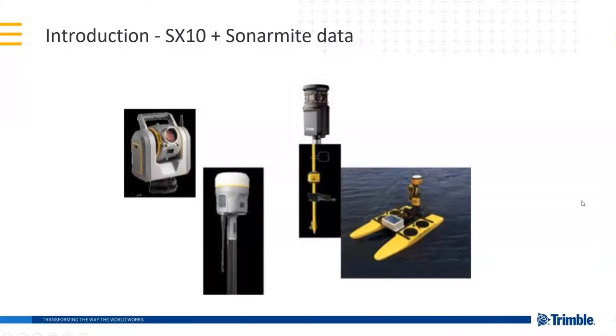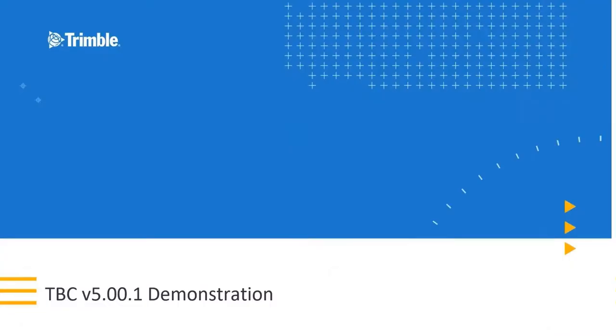Another thing about doing water work: if you're in a tidal zone, you're going to want to know what you're working with, whether it be mean low water or mean high water. All the depths that are coming out of my project here are not adjusted to mean low water, so it's just giving me a rough bottom.